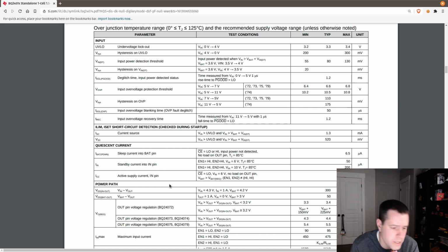All right, that 20 is just going to be a mystery for now, I think. It is sourcing the correct amount when it's in deep sleep mode. So that circuitry is correct. We'll figure out where that other current is going, and honestly, it could just be a state thing.